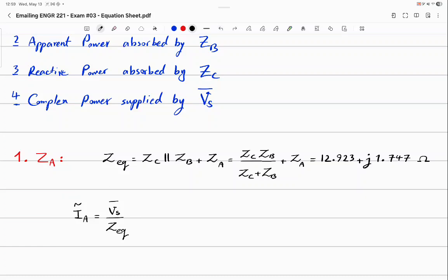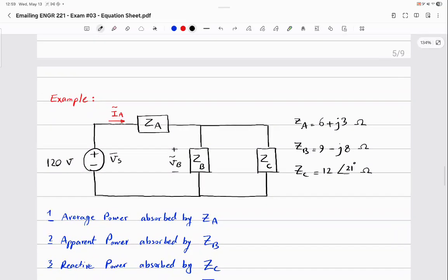Yes. See, we want to work with RMS values based on all the equations that we have. But the voltage that is given to you as the voltage source is not RMS value. It's just a standard value. How can you tell? Well, you might think that, okay, this is a bar, not a tilde. But that's not exactly very promising because the notation might be different in different textbooks.